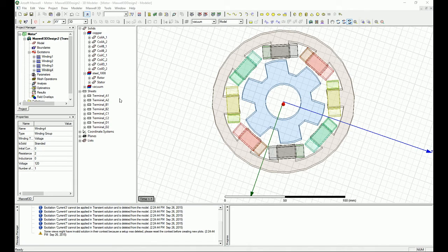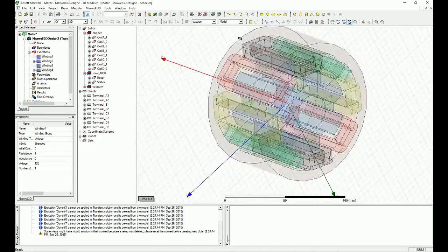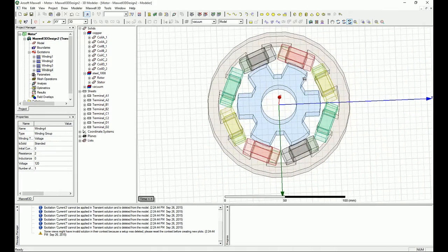Now, one other important thing that you have to take care of is how accurate your simulation is. The accuracy of your simulation is related directly to the accuracy of your meshing. To help the simulator do the right meshing, you have to give it some clue about which parts require finer meshing. Of course, the simulator is smart enough to refine the mesh each time the resolution is not achieved, but it's better to give it some clue so it does it faster.